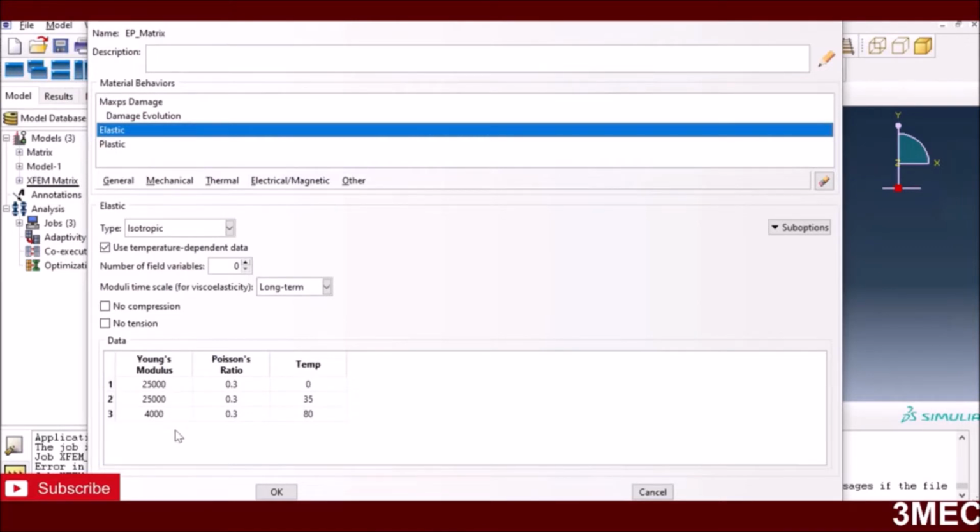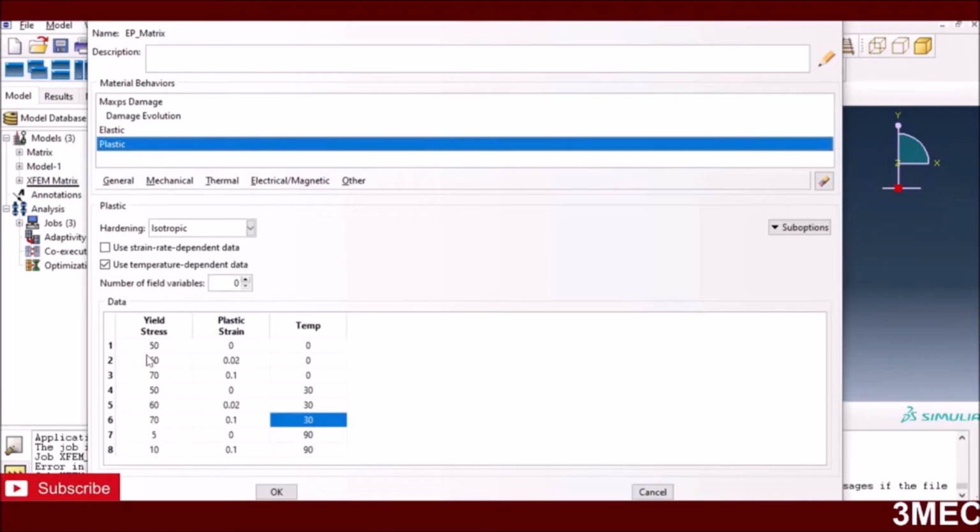So I have used elastic constants as a function of temperature, which will be useful later on when we will be doing thermomechanical analysis at the end, which will be part 3 of this video, when this matrix will be integrated with the shape memory fibers. The plastic part is again taken from the stress strain data given in that paper, and it was temperature dependent data, so that's what I'm using here.